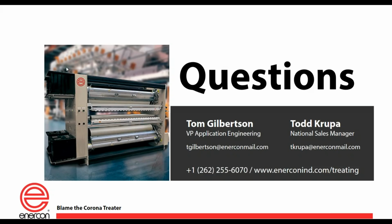Not film that has embossing in it or grooves in it or some sort of machining in it, whatever it is. And so what that means to you is it doesn't mean you can't do a Dyne test, but it means you're kind of going to be breaking your own ground with respect to the Dyne test method and your end result. Because there is no consistent way to read a Dyne number when the Dyne fluid is going into pits and valleys on the surface.